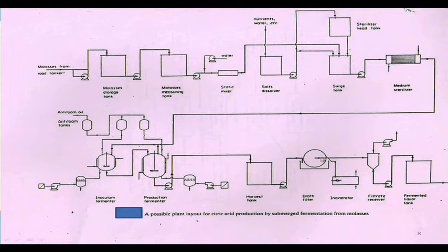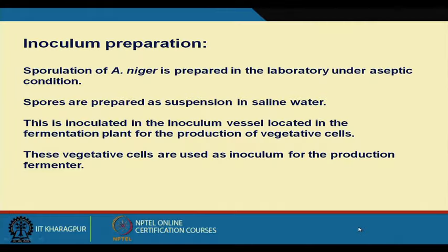So you have to remove the cell mass first by using the rotary vacuum filter, which I shall explain in detail. Then you take the filtrate out and put it in the filtered reservoir under a vacuum, so that the air content is low and oxidation doesn't take place. Then further purification takes place, which I shall discuss later.